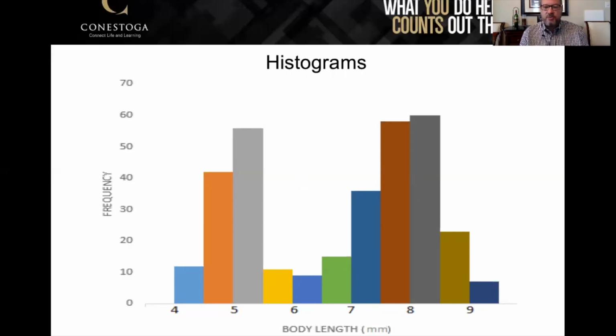So in this case, if I was building something and the expected length of the item was supposed to be, let's say, 6 millimeters, and you had a tolerance of 1 millimeter plus or minus, right? So it's supposed to be 6. It'll work if it's 5. It'll work if it's 7, but outside of that range doesn't work too well. And I saw this kind of a distribution. You go, hang on a second. Why am I seeing two peaks, both upper and lower, and I'm not seeing so much in the middle part, right?